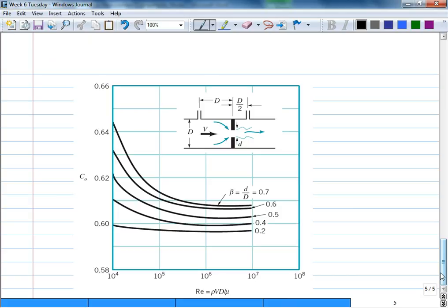You need to work out your Reynolds number first, again, same. If your data go down to 10 to the 3, you plot your points, something like that. Again, you'll be in a very narrow band, because although we vary the flow rate quite a lot, the Reynolds number range didn't actually change that much. So you may not get so high, maybe like that. Then again, you can discuss and compare.